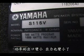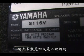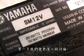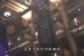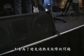All of the professional loudspeaker systems that Yamaha makes have nominal impedances of either 4 or 8 ohms, and that makes them perfect for use with most of the amplifiers on the market today, and we'll cover them later in the program. As a matter of fact, most professional sound companies do not operate systems with impedances of less than 4 ohms, again, mainly to avoid the heating and risk of failure.